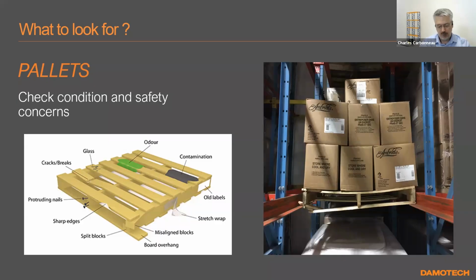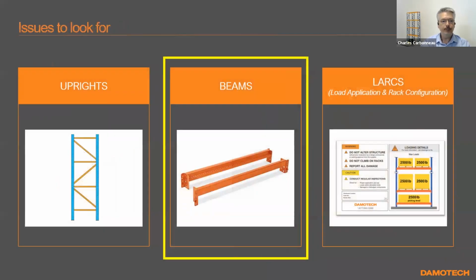Of course, you want to change them or fix the problem, but more so, ask the pallet manufacturer if it's okay to use these types of pallets in a drive-in, like the situation in the picture on the right. It's not made to go in a drive-in. It's too flimsy a pallet to be able to do that. You can see how much deformation you have in there. It's broken on one side, so that's a typical sign that you have to change that pallet.